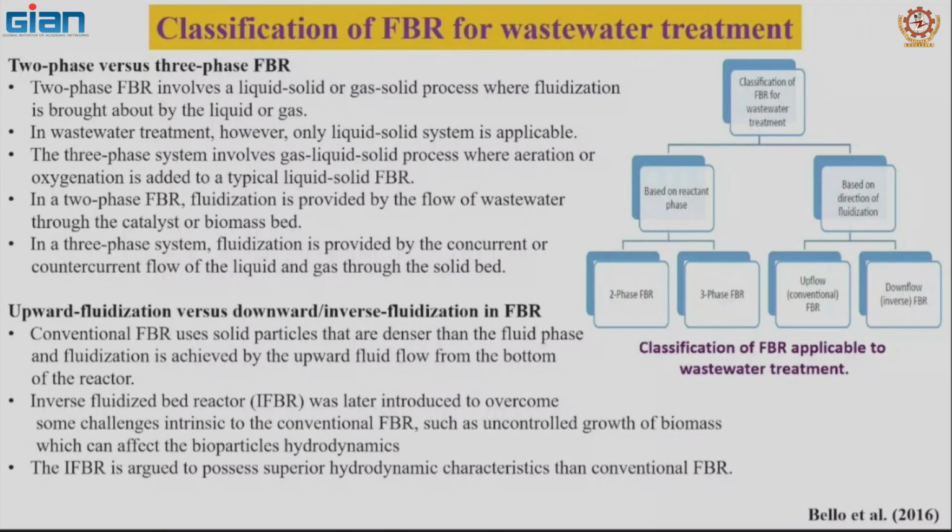And a three-phase system involves a gas-liquid-solid process where aeration or oxygenation is added to a typical liquid-solid fluidized bed reactor. In a two-phase fluidized bed reactor, fluidization is provided by the flow of wastewater through the catalyst or biomass bed, and in a three-phase system, fluidization is provided by the co-current or counter-current flow of the liquid and a gas through the solid bed.